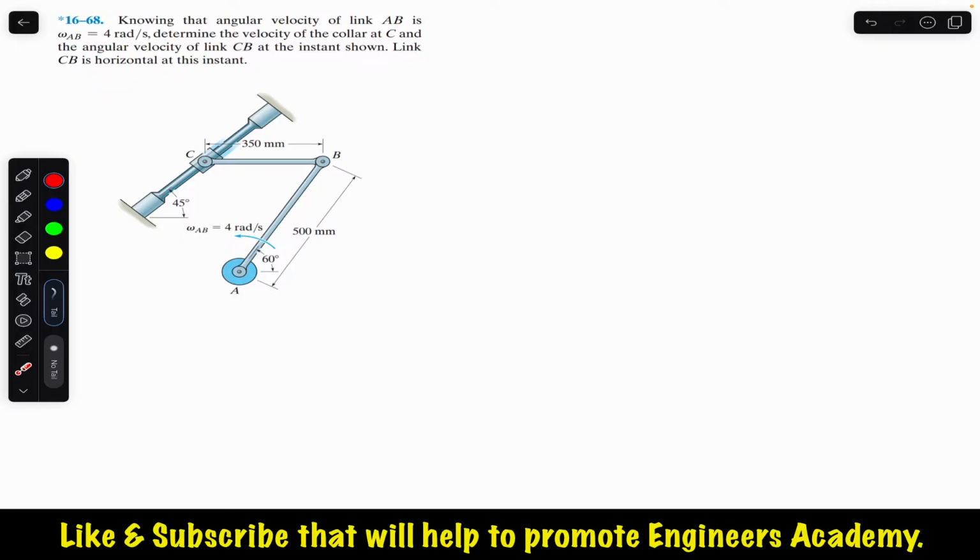So now if this link AB has an angular velocity in the counterclockwise direction, this point B will revolve about that point A in a circular path of radius equal to the length of link AB. So this point B will move up, and as a result, this point C will move downward in this direction. So let's draw the free body diagram.